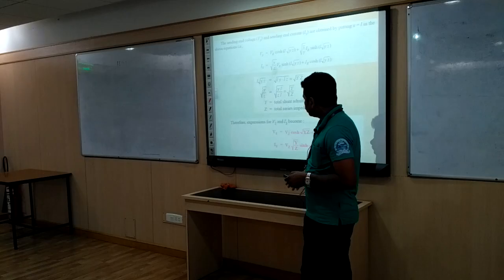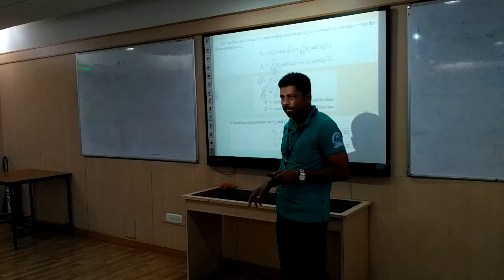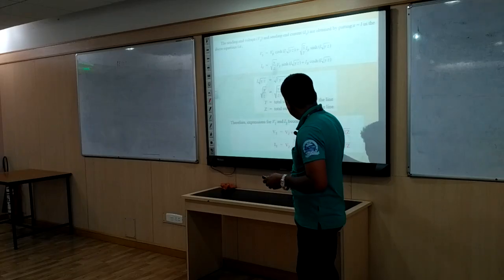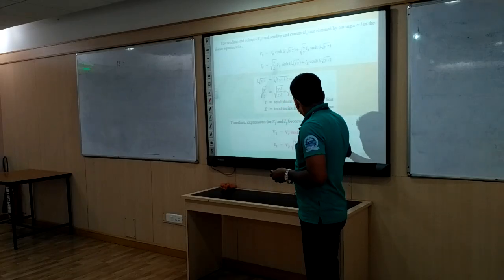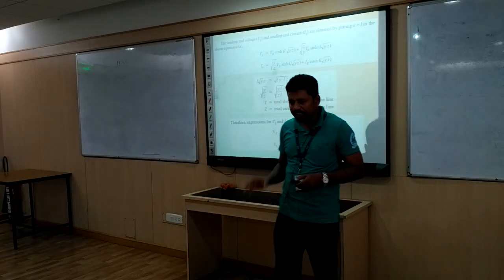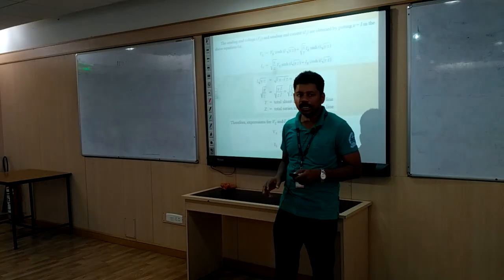After finding all those things, the final expressions for sending end voltage and sending end current are: Vs equals Vr cosh of root of yz, plus IR into root of z by y into sinh of root of yz. Similarly, Is also you have to find. So this is the final expression for the sending end.